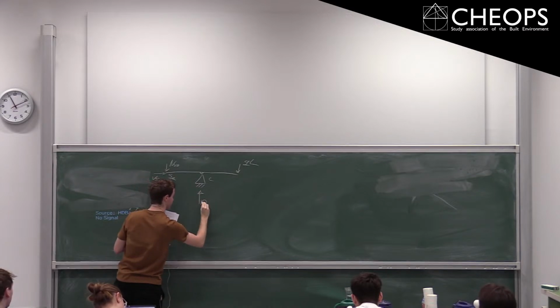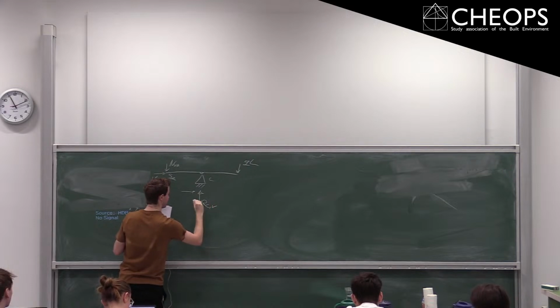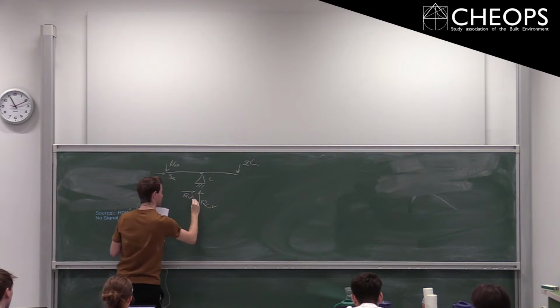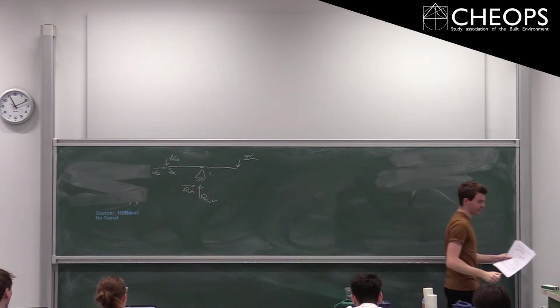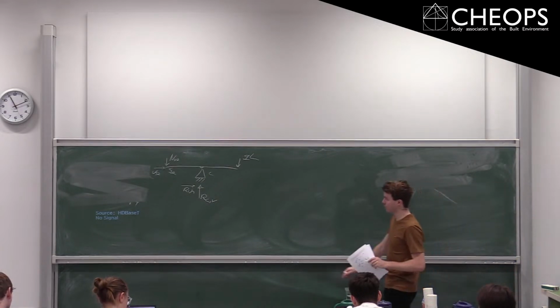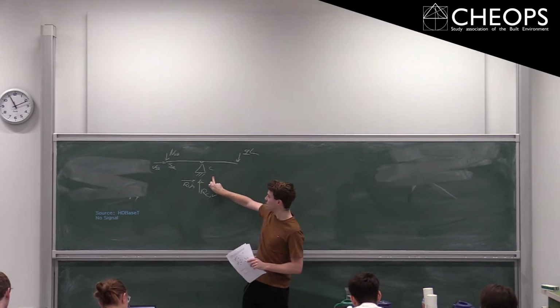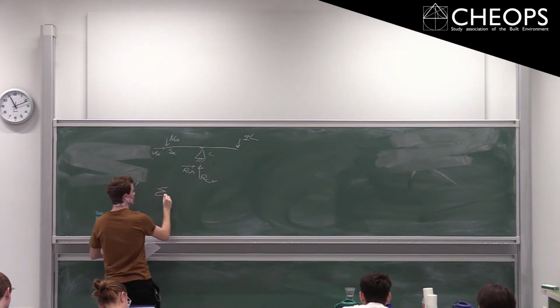So RC vertical and RC horizontal. And now you simply use equilibrium to find, well, your internal force. So what you can do actually is just do moment equilibrium about point C, because then these two unknowns are also cancelled, so you don't even need to bother with those.